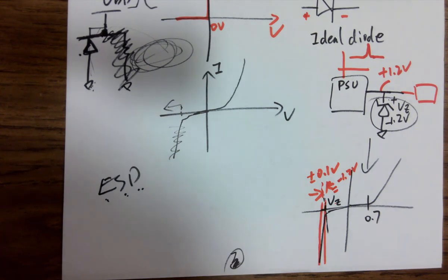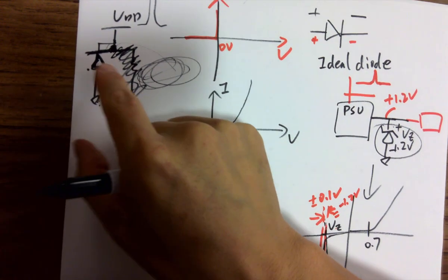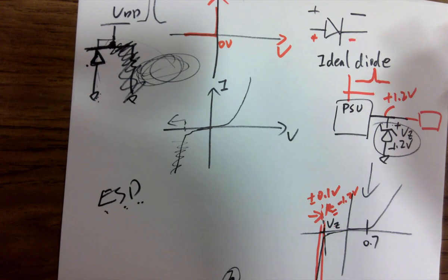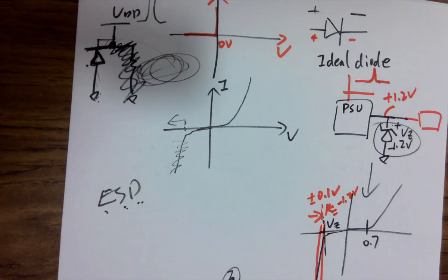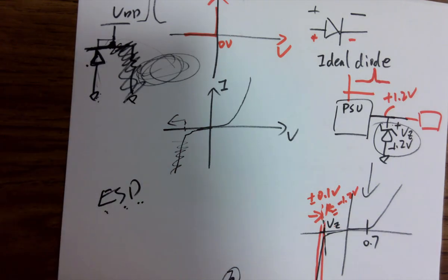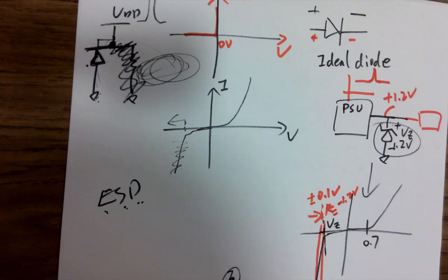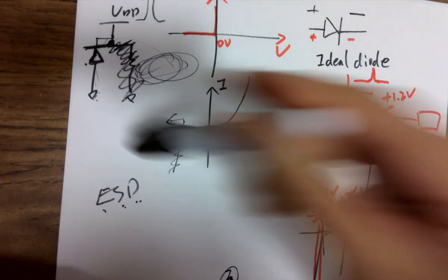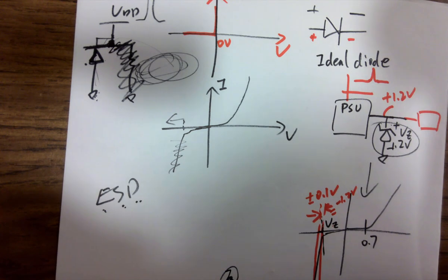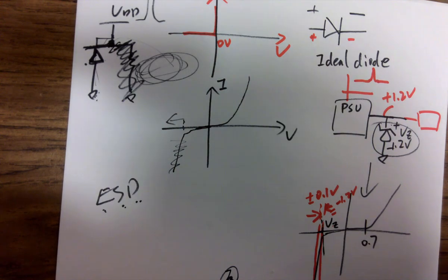But for now, just know that by using the regular diode's property like this, you can protect the following circuits, and it's called a clamping circuit. This restricts the voltage to a certain range, so it's not surpassing that range and damaging the following circuit. For example, the integrated circuit we designed and fabricated with TSMC last year. Every single chip requires ESD protection diodes, and you don't even need to manually design them every time, because everyone needs it. So they directly placed them into the pads.